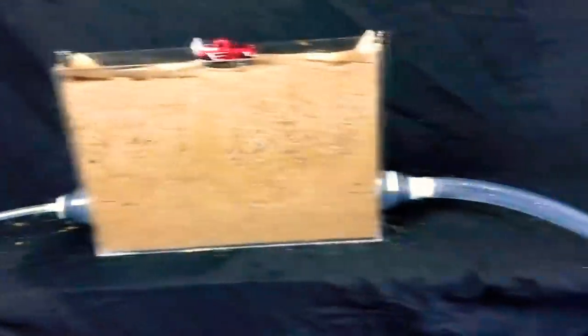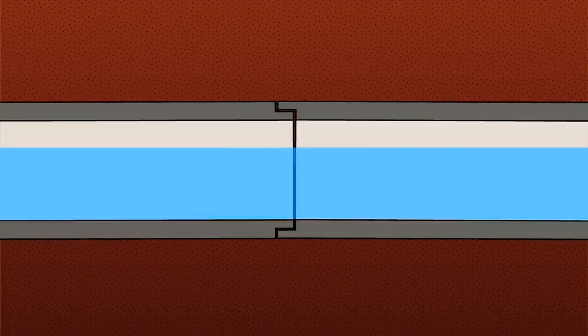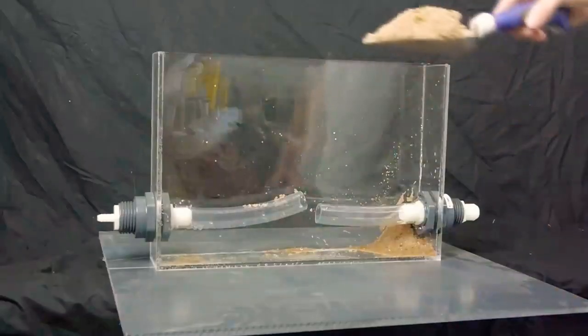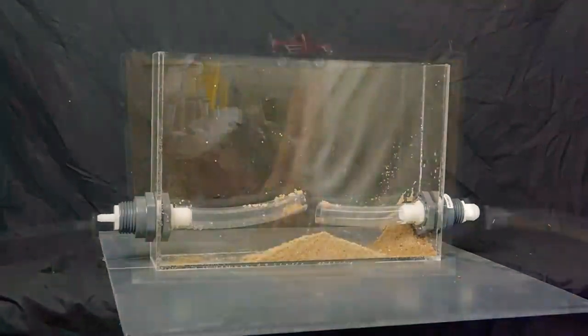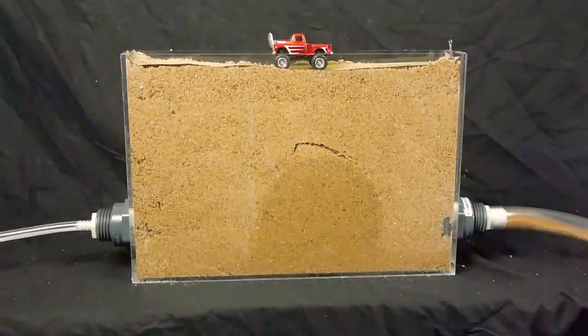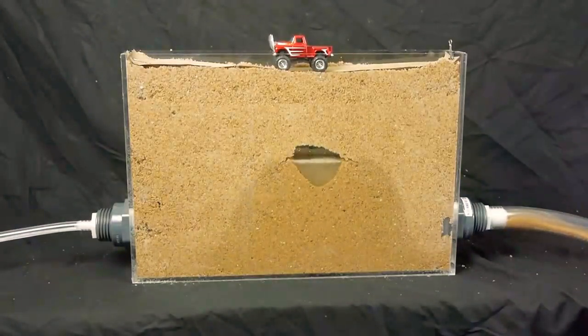Unfortunately, we can't see into the ground, so I built this demonstration so we can see for ourselves how this works. All it takes is a little bit of settlement or shifting to create an opening in one of these pipes and allow internal erosion to start. I added a gap in my pipe to simulate this effect. Water moving through this pipe is able to dislodge the adjacent soil and carry it away. Notice there's no signal on the surface that anything is awry.